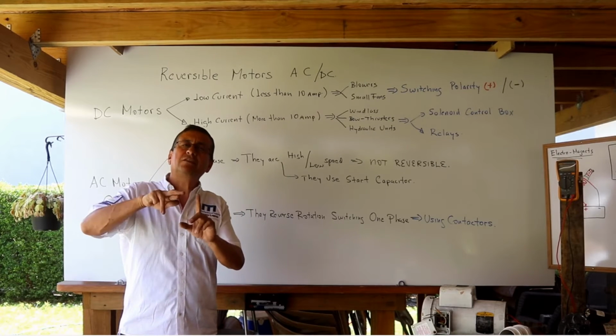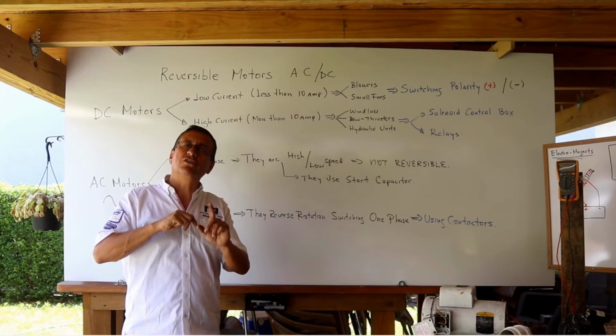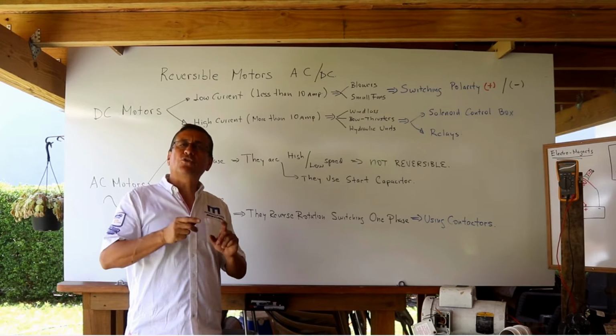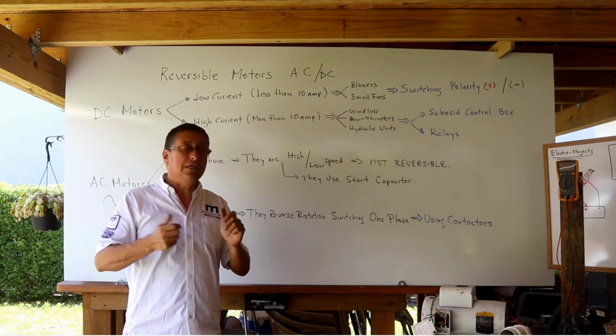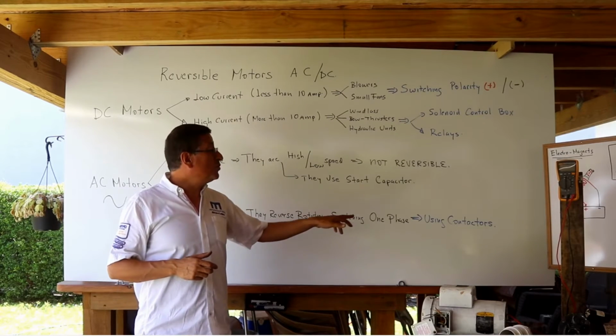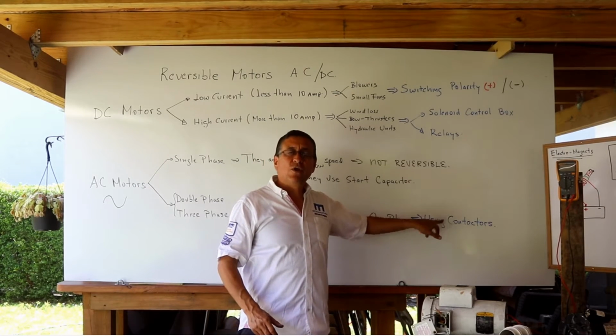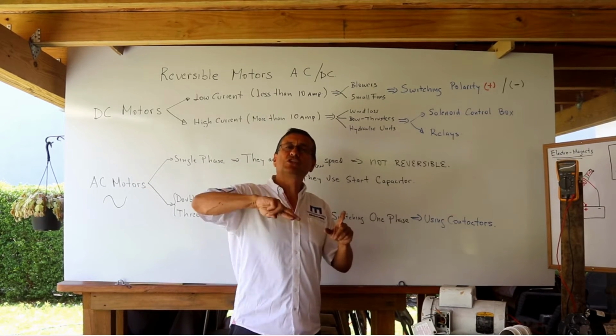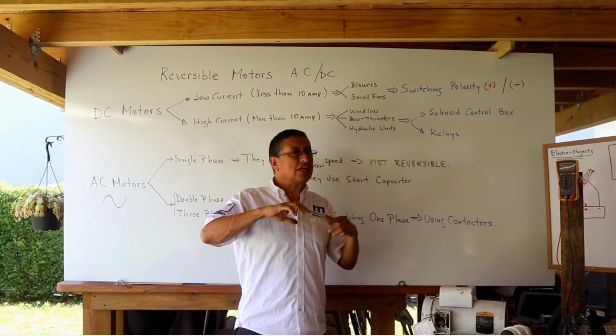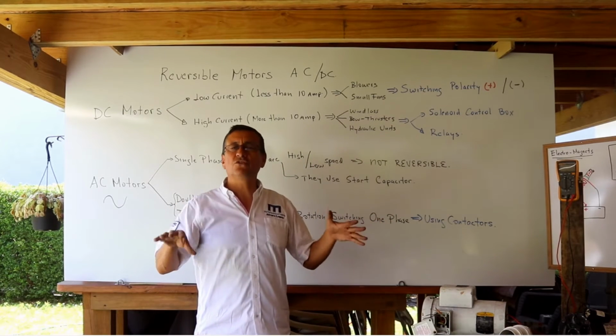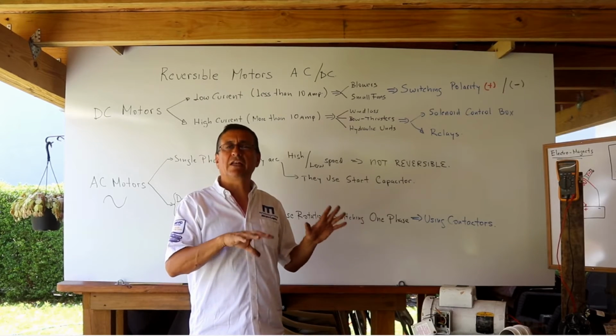You need to switch two phases and immediately the rotation changes. I am going to explain right now the procedure to do that easily. Basically, you need to use contactors. When you use contactors, you can switch the rotation. Contactors are commonly used in millions of applications.